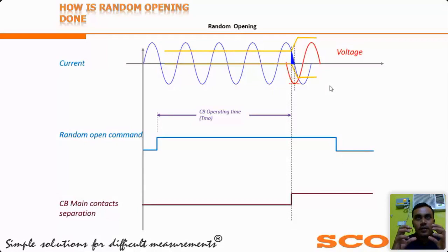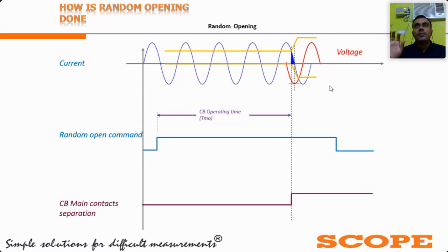In the open situation, the circuit breaker's mechanical contacts separate, and after some arcing, the contacts become open, and only then does the breaker become electrically open. So here we can see, at this instant, before current zero, because it is a current graph, the breaker has been electrically open.